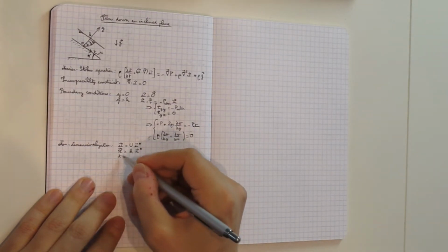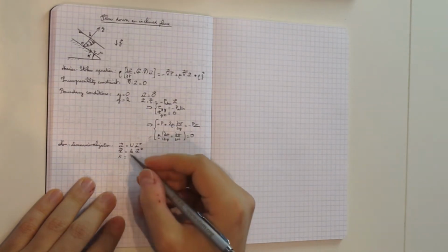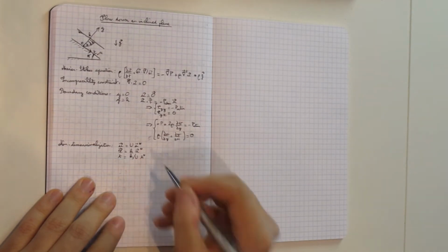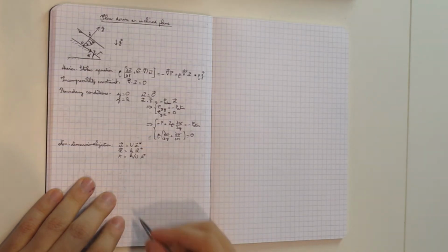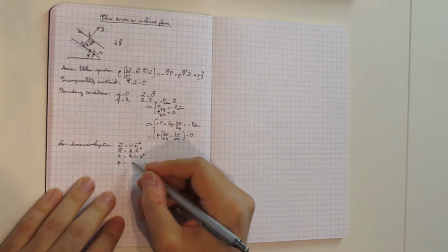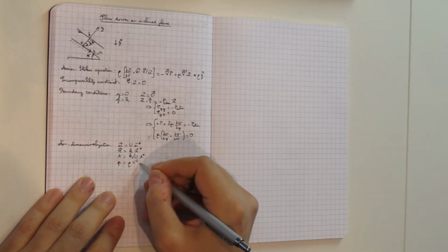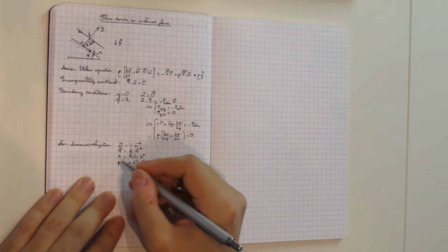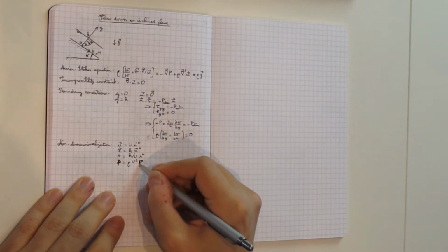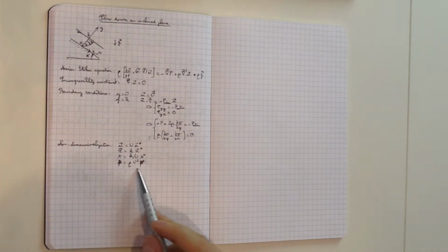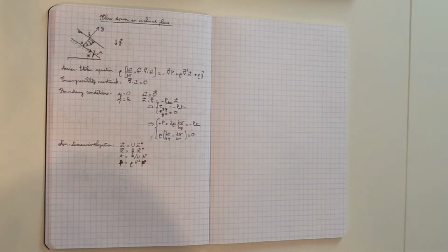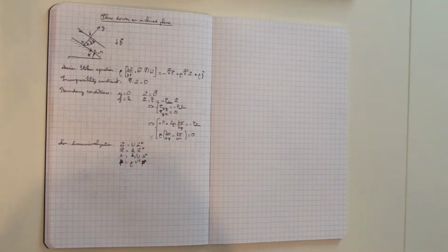Then for time, there's no need to introduce any other quantity because we can use h divided by U as a unit of time. And for the sake of defining a scaling quantity for the pressure, I'm just going to use rho U squared, so that's just going to be P equals rho U squared times capital P. These are capital P's in here. Okay, and that's going to give me my scaling quantities for my equations and boundary conditions.